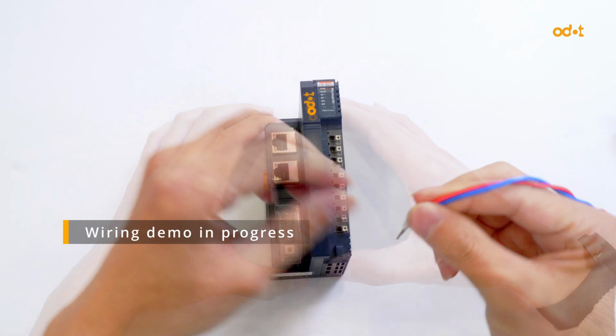Right-click on the module and choose Details. Uncheck Auto Assign IO Names. Manually change the IO name suffix to 2. Next, switch to the network topology view. Connect the PLC's network port to the module's port 1. And that's it, topology setup is done.